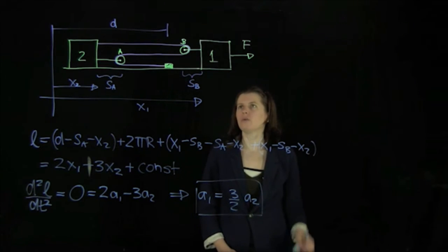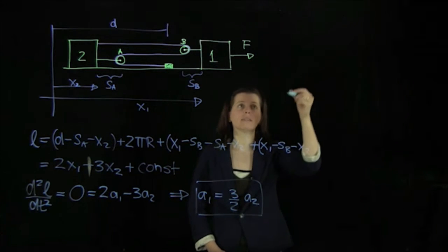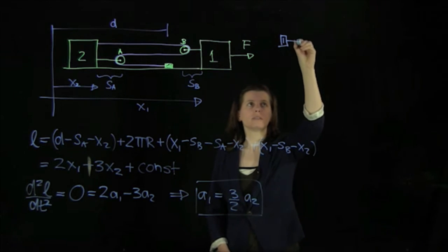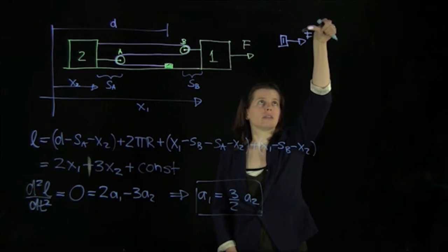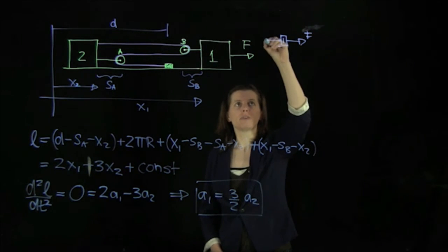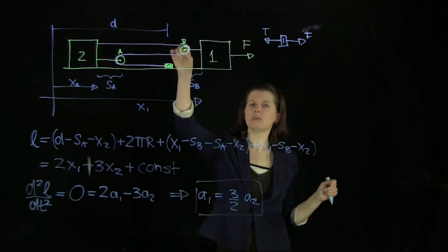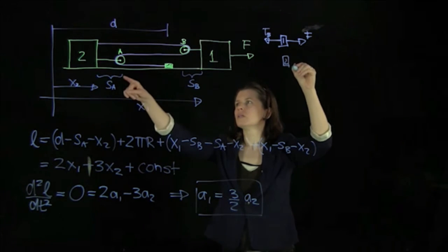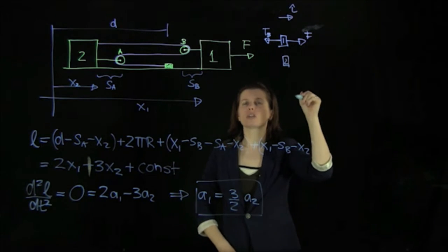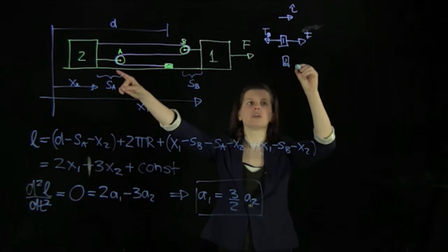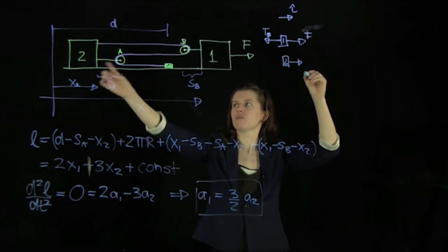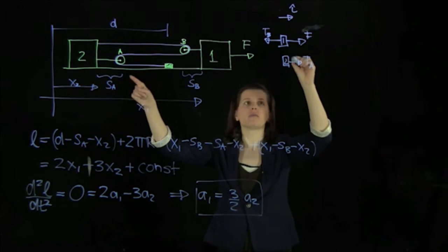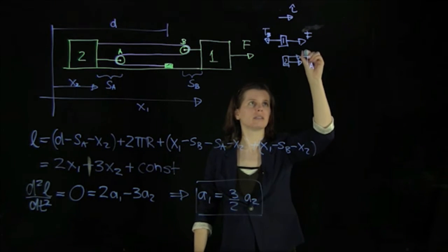For now, we need to continue with setting up free body diagrams of all 4 objects. Let's start that with object 1. What's acting on object 1? Well, we have F here. We're just going to write it as magnitude. We have F, and then we have here a tension that goes to the pulley B. That one is different from the tension in the string, so we're going to call this TB. Then we have object 2. And of course our i hat goes in this direction because it follows the motion of the objects. We have here kind of the reverse. Now we have a tension of this string here that's attached to pulley A, but it's different from the string tension. That's a specific one, TA. And we also have a T from the string here, so we'll add a T.